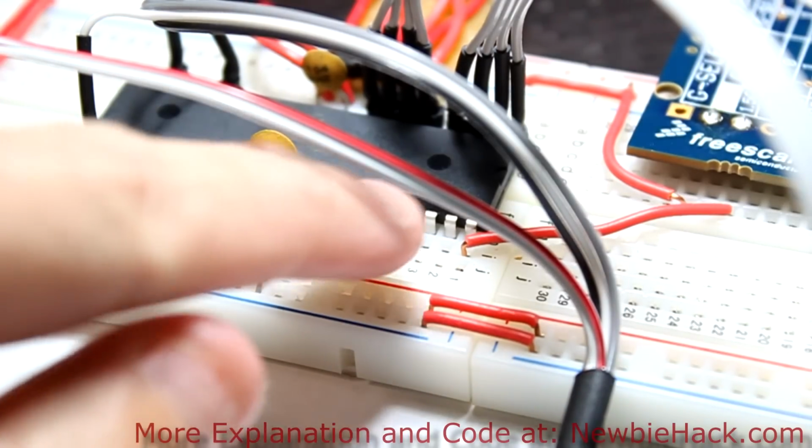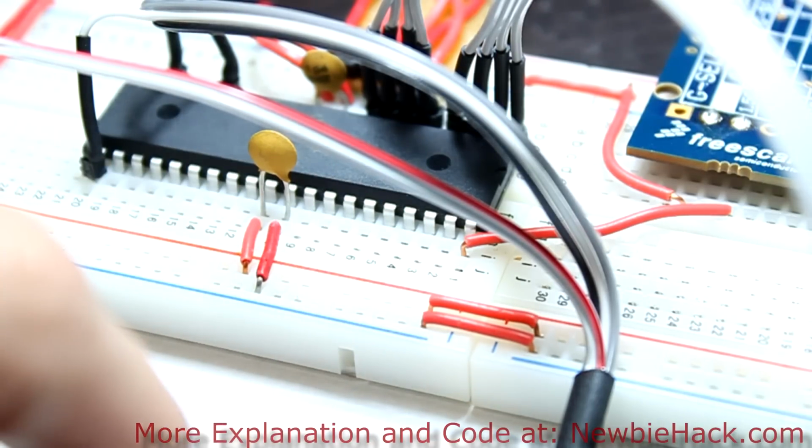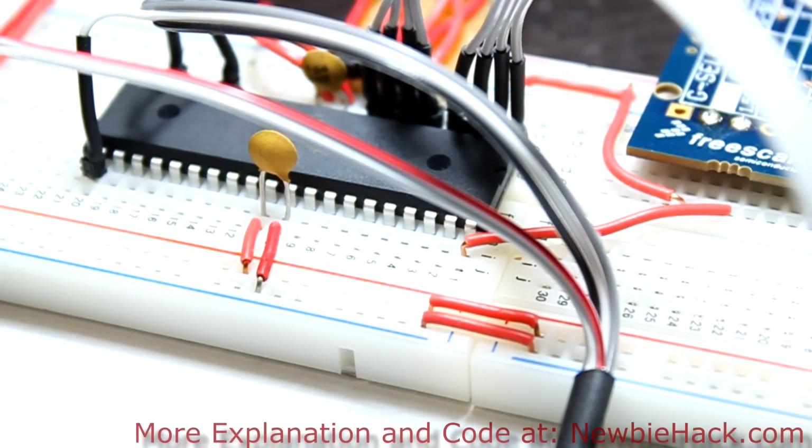In the circuit we had a capacitor in this location, and I removed it for this part of the demonstration, so we can see what the deflection is without the capacitor. We'll try it with the 10 UF capacitor, and then we'll try it with the 100 UF capacitor.